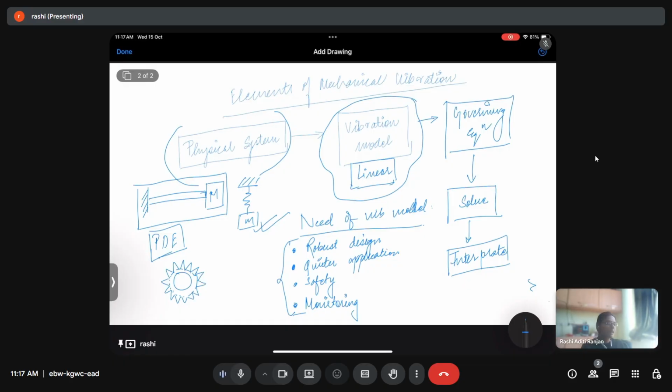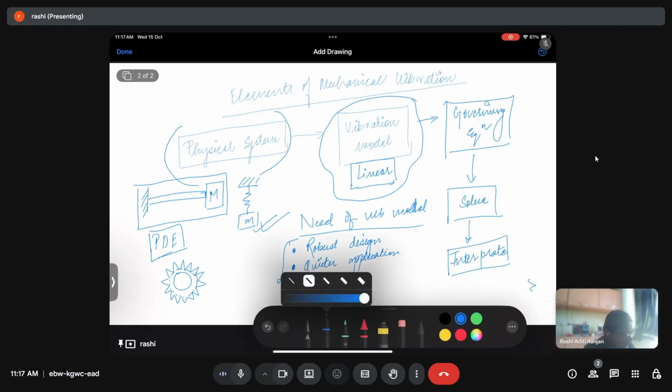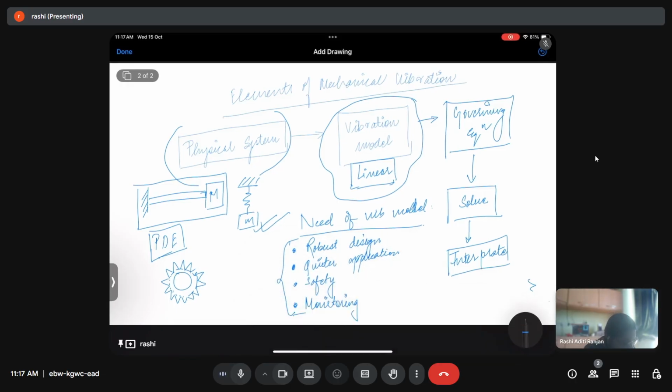Now what happens is that due to operations, due to continuous meshing of one gear with the other gear, some kind of a chip is created on the gear. Chip means a chipped tooth, which means this. It got blunt from here. Now what is this going to create in the final result? This is now going to give us different vibration data.